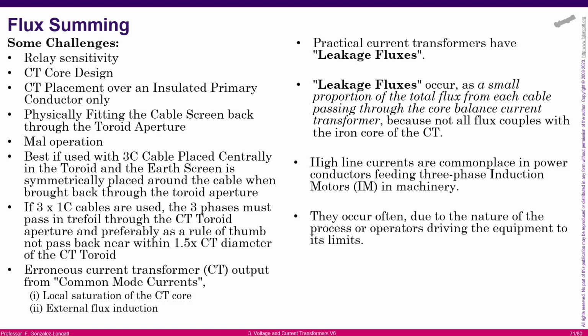this. Another thing is that the fluxes that are moving across the magnetic core can be affected by other fluxes. And also the flux can be affected by something that is called the leakage flux. Okay? What is happening? What is the leakage flux? Well, the leakage flux is mainly a situation where some part of the flux that is passing across the cable goes beyond the magnetic core, and as a consequence you don't receive that flux in the core, and you lose some coupling between the flux and the currents.